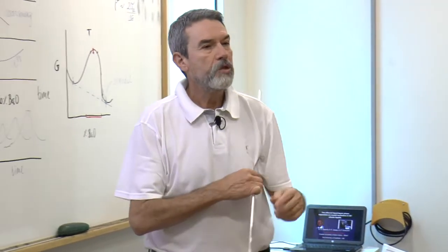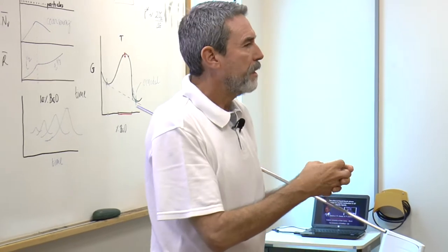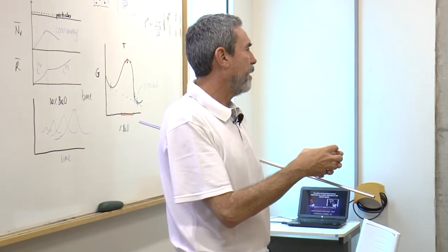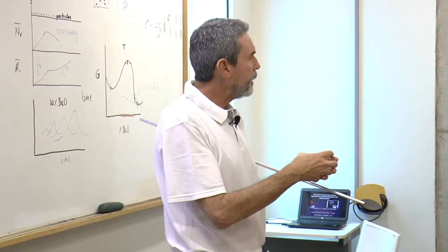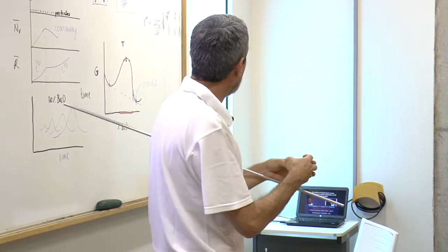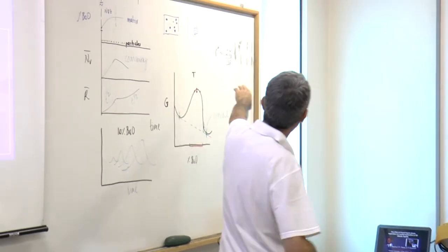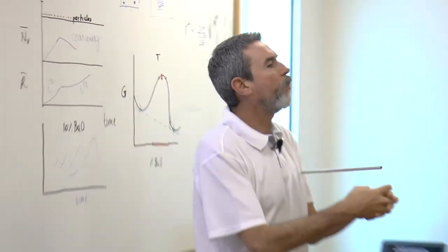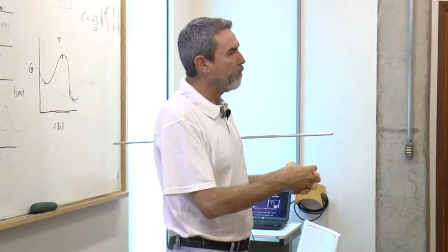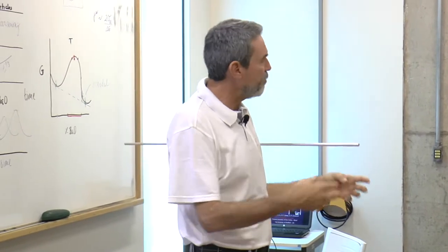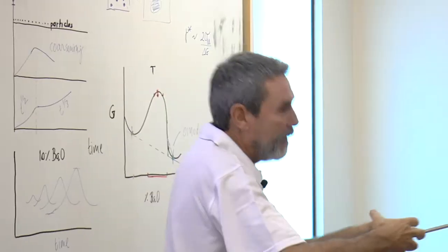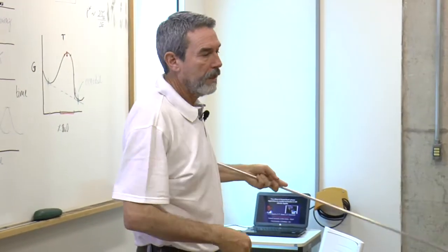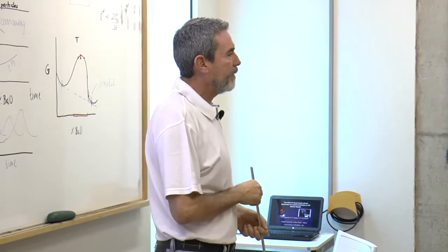He is asking, are 2 or 3 atoms enough to distinguish one phase from the other? Not yet. If 2 or 3 atoms are below the critical radius, they will form and dissolve. They will form these fluctuations, they form and dissolve, form and dissolve. Once they reach the critical size, then they are able to grow. And this can be calculated.